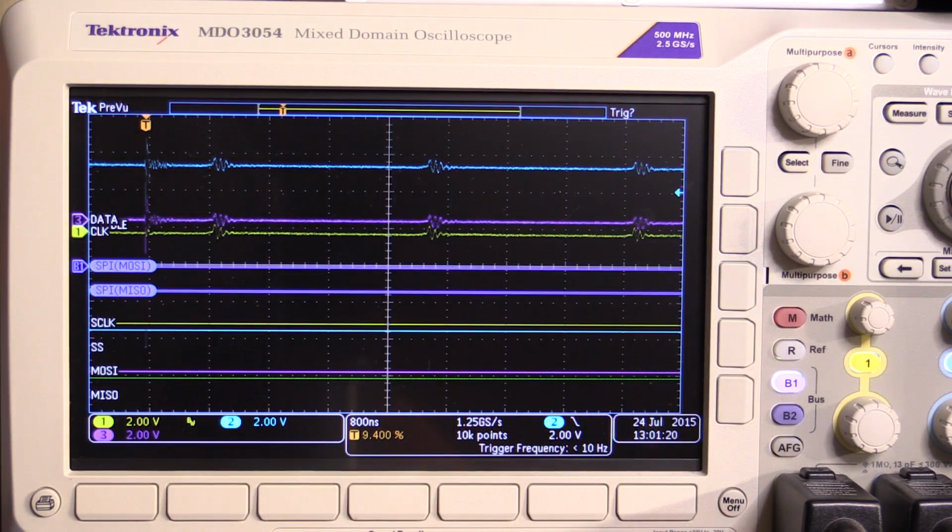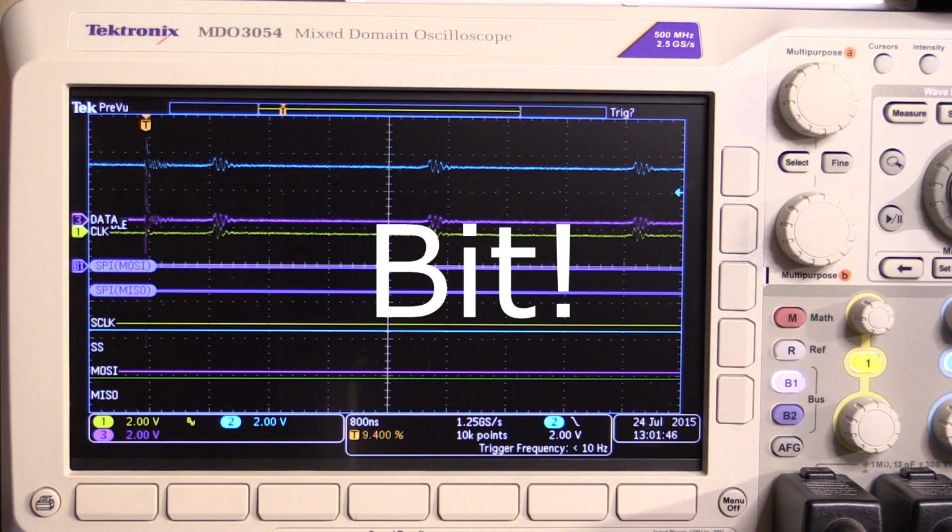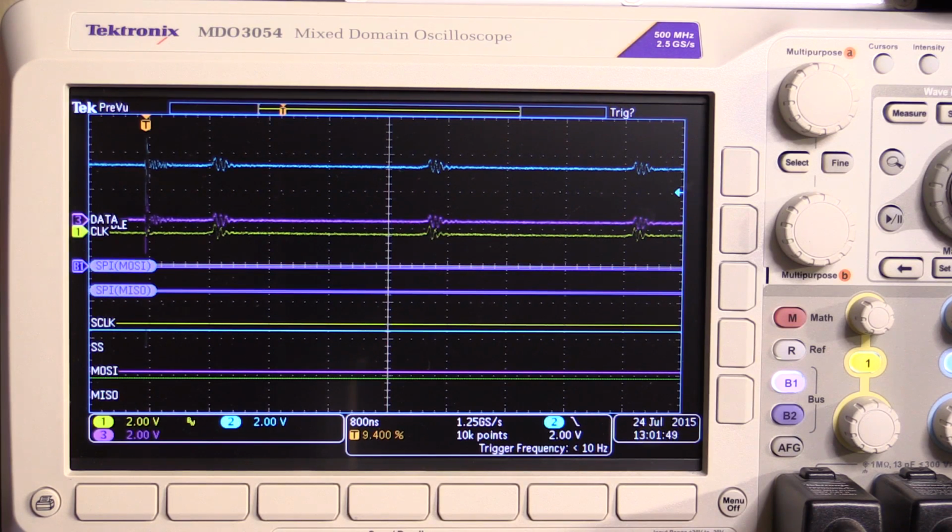The DAC8734 is very typical of a lot of SPI DACs in that they have an offset register, which is effectively an address within the chip, typically a single byte value, which gives you up to 255 registers, or a few registers and maybe some initial control values. And then you have, in this case, a 16-byte data packet that goes out. If you write that to the control register, you can use it to control various aspects, like the GPIO. If you write it to one of the DAC registers, then that becomes the value for the DAC, or the calibration registers, which are higher up.